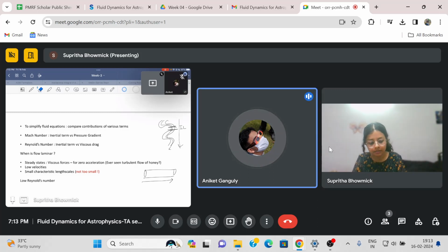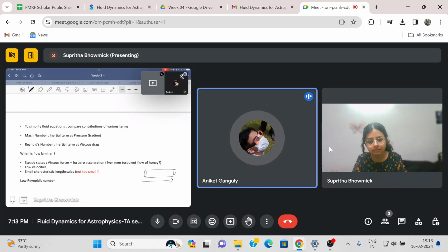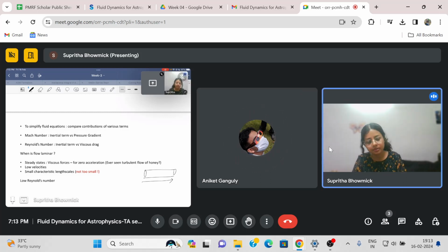Like in a Poiseuille flow, we have this pi p r to the 4 divided by 8 mu L. In that case, that L is that characteristic length, right? What is L in there? No, that flow through a pipe, the length of the pipe. Yeah. Absolutely, correct.